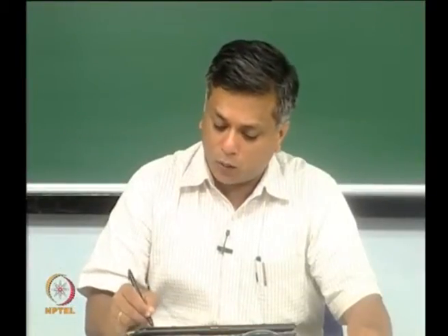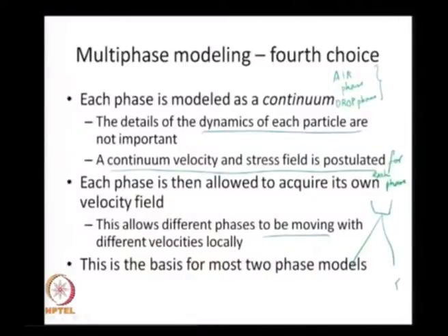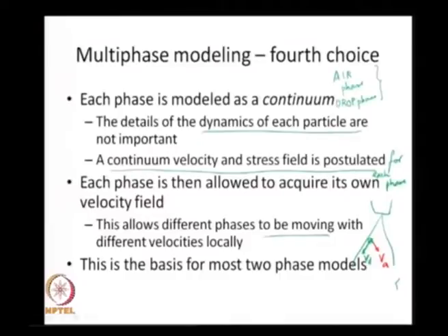So, if I take a spray for example, say if I take a region here, the drops probably want to go in this direction, but the air may want to go in a slightly different direction. The reason for this is actually due to entrainment. The spray is like a jet and the jet entrains air from the outside, and essentially this is like a representative streamline.